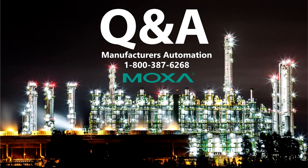Another question here from Chris. Chris wants to know, what are the most important features for explosive gases, natural gas environments? Well, most of it's going to have to do with being internally sealed. So essentially anything that can create a fire, intrinsically safe is the buzzword here. Any electrical communication within the unit shall not and cannot be able to ignite any external gas.